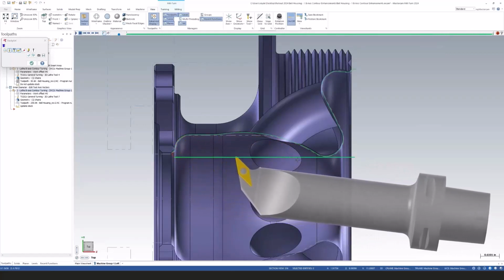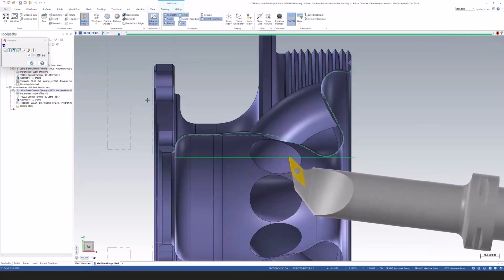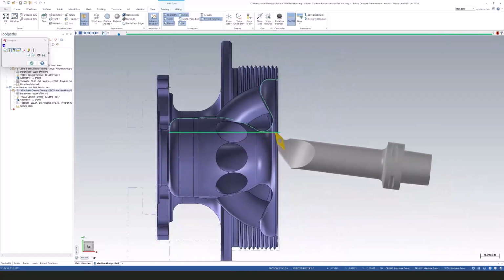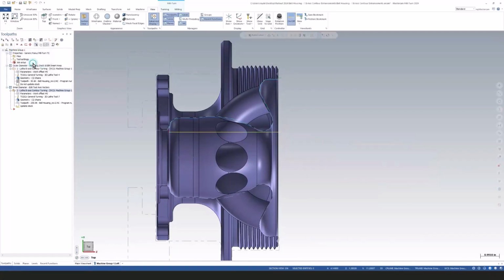We've got a really tight retract here, right? You might want to increase it, give that a little bit more clearance to decrease the pucker factor on that one, but that's going to really simplify things. And you'll notice with two toolpaths, we were able to finish all the faces on this very quickly and easily.